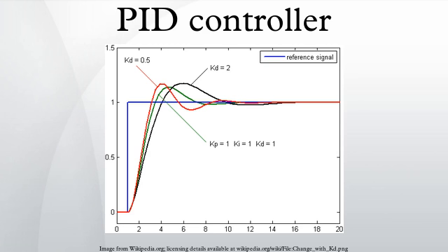Loop tuning. Tuning a control loop is the adjustment of its control parameters to the optimum values for the desired control response. Stability is a basic requirement, but beyond that, different systems have different behavior, different applications have different requirements, and requirements may conflict with one another. PID tuning is a difficult problem, even though there are only 3 parameters and in principle is simple to describe, because it must satisfy complex criteria within the limitations of PID control. There are accordingly various methods for loop tuning, and more sophisticated techniques are the subject of patents. This section describes some traditional manual methods for loop tuning.